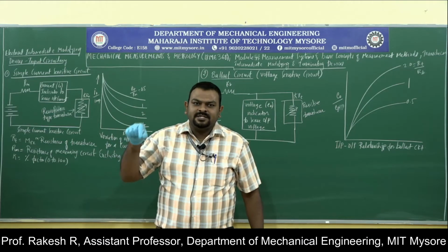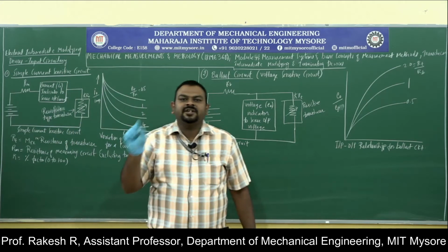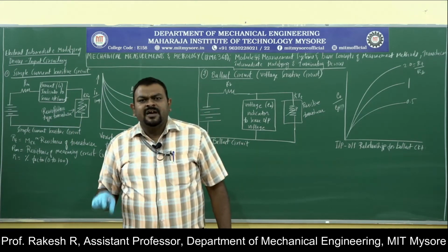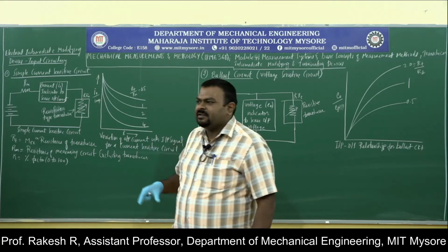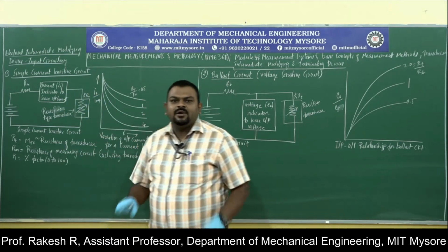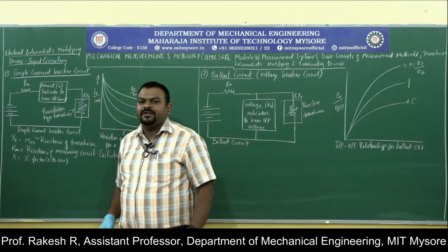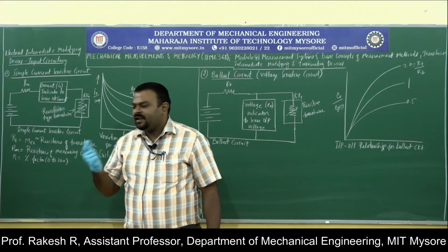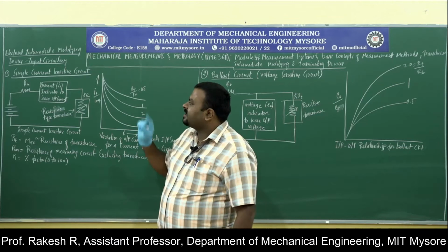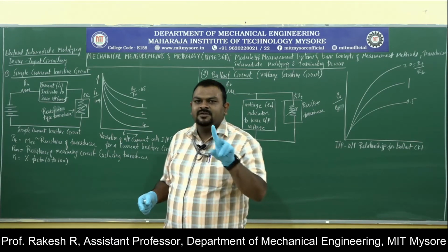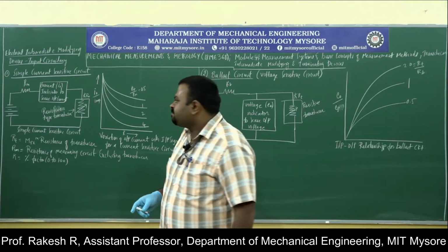If the amplification is done only based on voltage, then I have to choose voltage amplification as the intermediate device. If I want high power, high impedance, then I need to design for impedance, or a power amplifier, as the intermediate modifying device. These two are very important design considerations while considering electrical intermediate modifying devices. There are two things, one is voltage amplification and another one is power amplification.